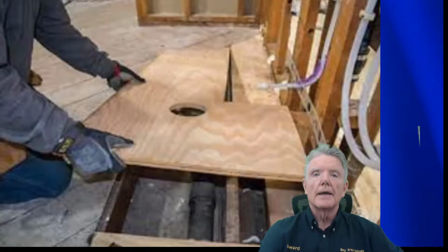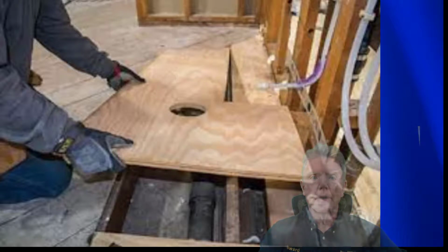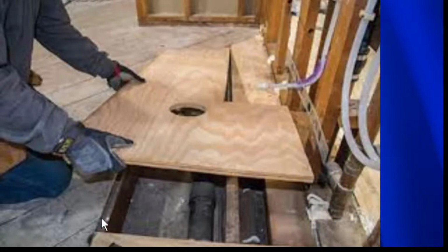So let's review one more time why this kind of repair is a problem. What they've done here is when they did this repair, they tore all the nails out right here. And so if we take this piece of plywood and we set it on top, it's going to be supported by this board here and then this board here. We set it down there and we put a few nails in it. What's going to happen is it's going to come this way, it's not going to be connected to this, so it has nowhere to go because they're just simply not connected. They're not glued, they're not nailed, there's nothing between them. So what we have to do is figure out a way to connect this board to this new piece of plywood so that the earthquake force will transfer as we want.